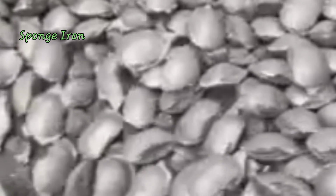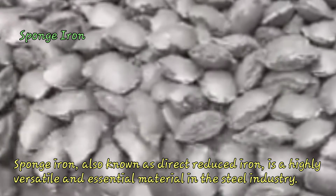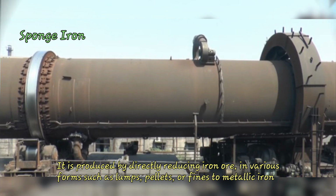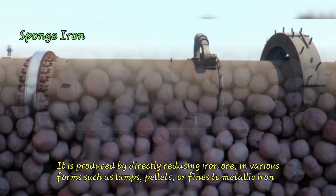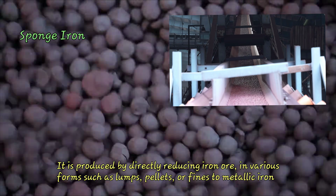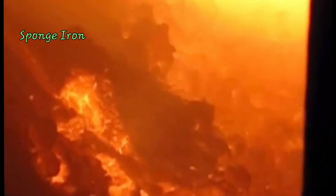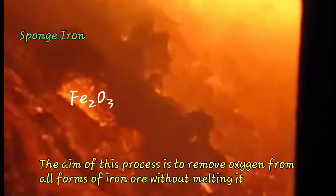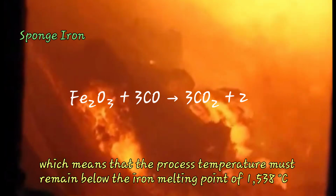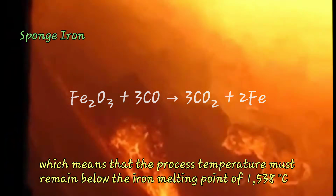2. Sponge iron. Sponge iron, also known as direct reduced iron, is a highly versatile and essential material in the steel industry. It is produced by directly reducing iron ore, in various forms such as lumps, pellets, or fines, to metallic iron, using a reducing gas or elemental carbon derived from natural gas or coal. The aim of this process is to remove oxygen from all forms of iron ore without melting it, which means that the process temperature must remain below the iron melting point of 1538 degrees Celsius.